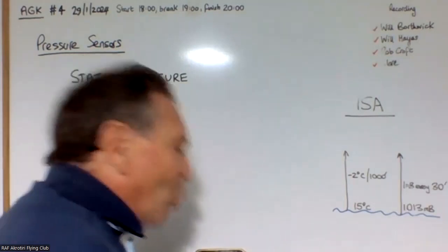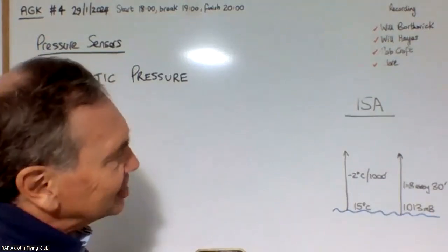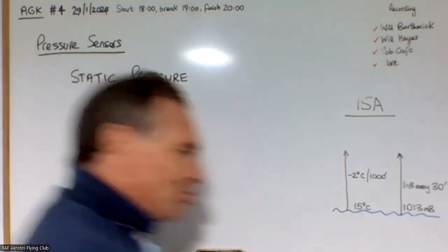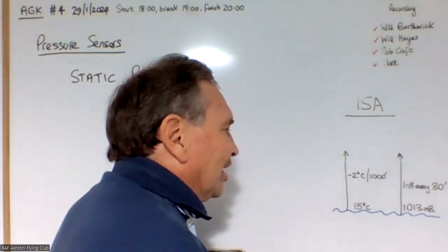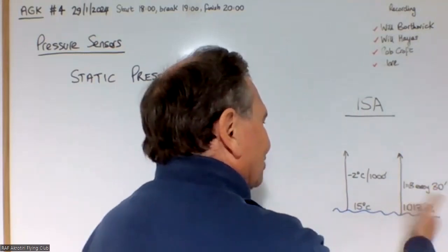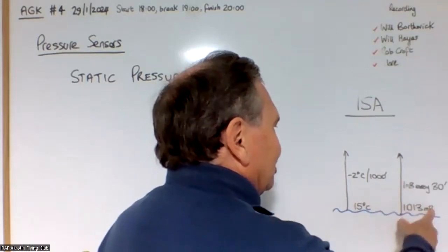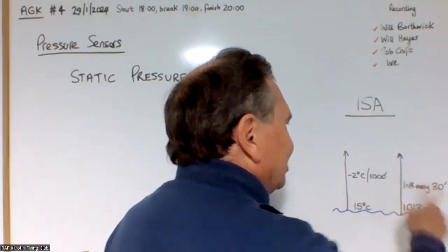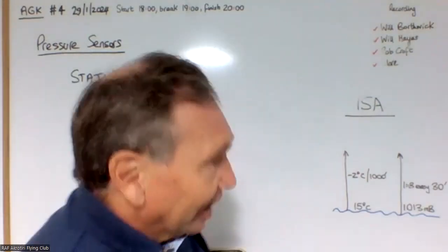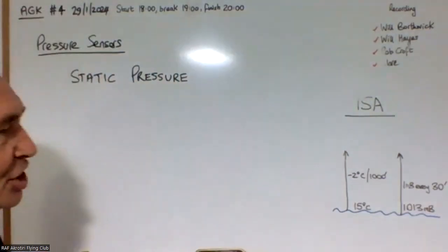So in actual fact the pressure as you go up into the atmosphere changes an awful lot very, very quickly, doesn't it? Whereas you find that the difference between a high pressure day and a low pressure day might only be sort of like 50 millibars or something like that. But you see, this is changing by 1 millibar every 30 foot. So that means that you don't need to go that high to have quite a dramatic change in air pressure.